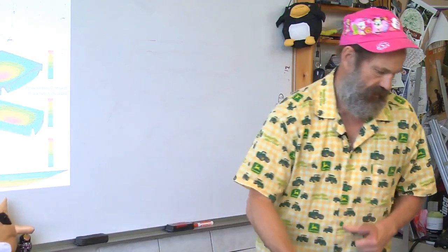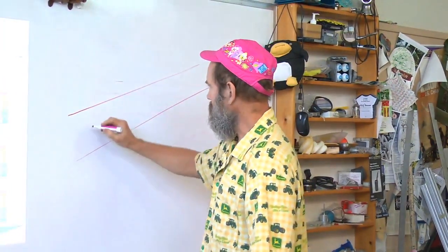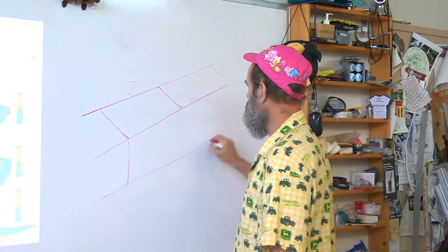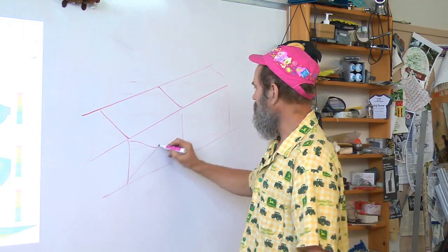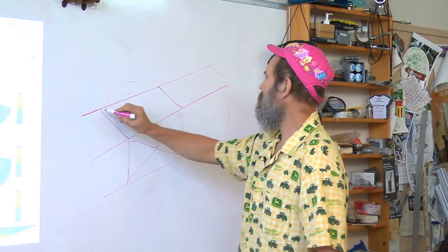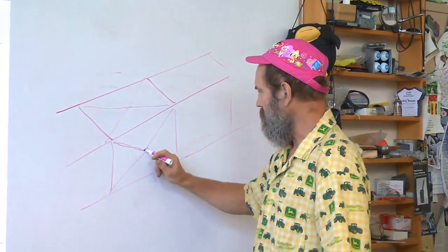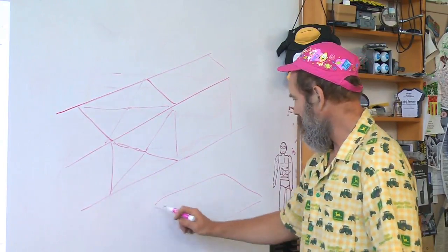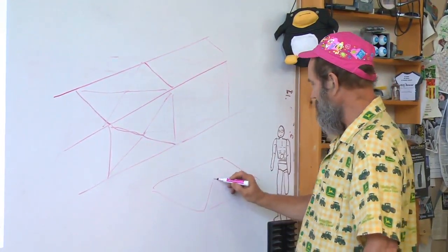Looking at heating, ventilating, and air conditioning ducts. Why? I mean, here's a piece of ductwork, and here are these sections that are put together to form your air duct. Why do these sections often look like they've got these crosses in them? And when you look more carefully, indeed these are creases. And what happened was a flat plate was taken and it was formed, bent, such that it's a mini pyramid.